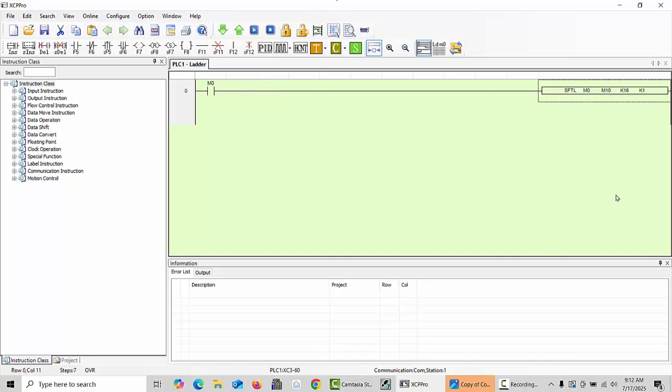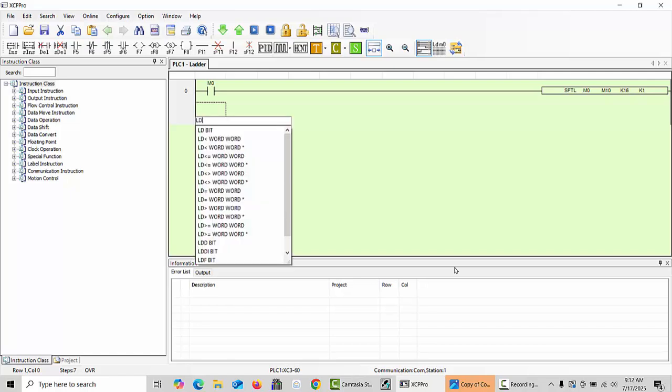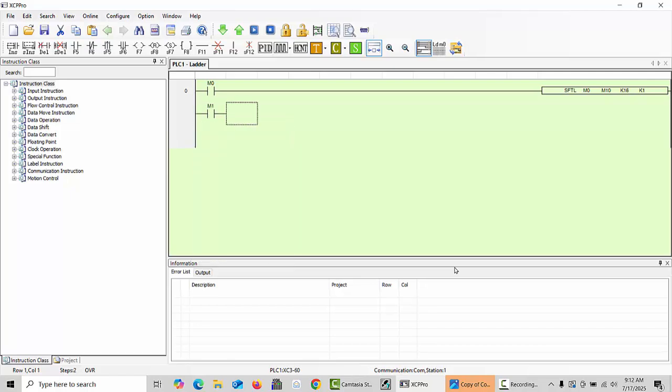This is very simple: if you'd like to move any 1 bit from right to left, you type this symbol. In the next rung, we take, for example, LD M1, and next we type SFTR, because this one is used for the opposite direction, left to right, and now we need to move the bits.